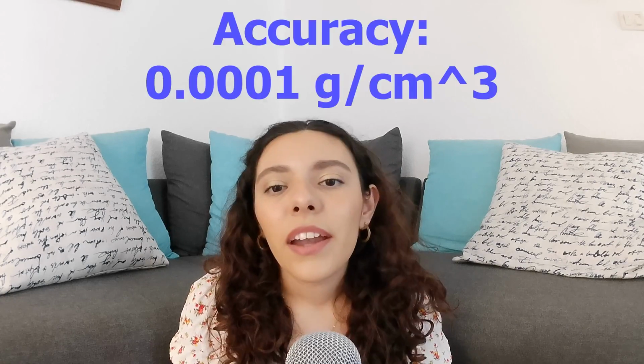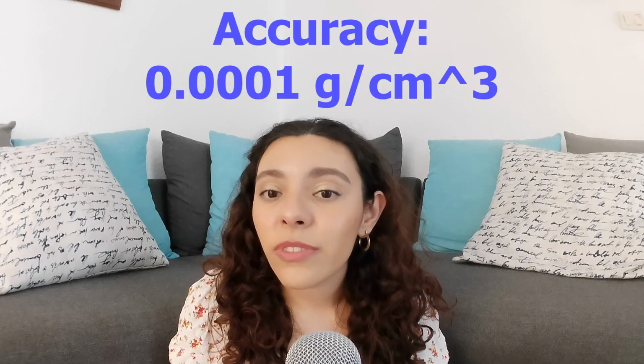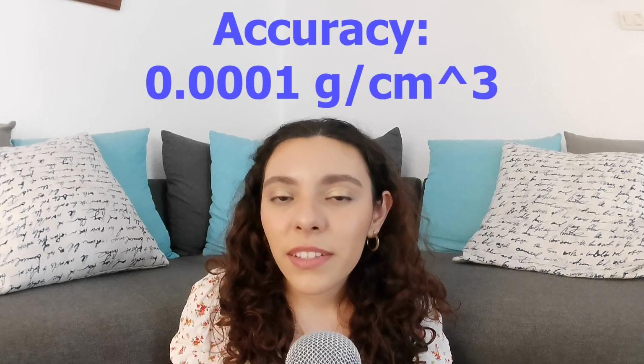Refractometers are not influenced by undissolved solids or dissolved air. Its minimum field of measurement is 0.004, and its accuracy is 0.001 grams per cubic centimeter. Sticky liquids or suspended solids can coat the prism, so it would need a periodic cleaning that can be automatic with intermittent steam. They are used in evaporators, in the concentration of black liquor in the paper industry, etc.